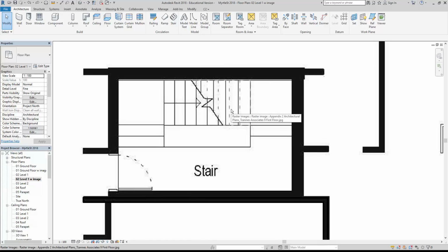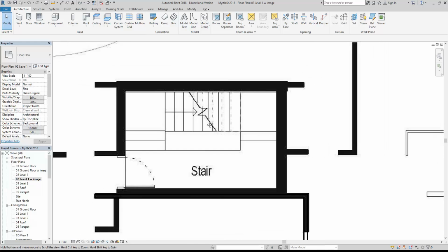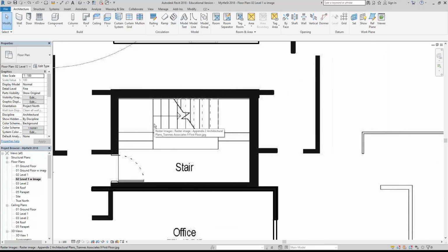It's a nice thing to do from a design point of view because it saves you space, but from a construction point of view, it adds a lot of complexity, and maybe also it means that you have to think about the headroom that you'd have within the stair itself, because the top flight is going over your first flight, so you have to think about the distances between the stairs while you're making the stair. Whereas normally all you need to think about is the headroom from your stair to the floor above or the ceiling that you're walking under.